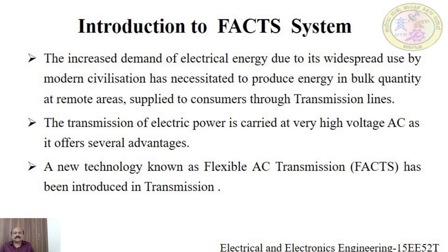First and foremost, the high voltage reduces the total amount of the copper material or conducting material used in transmission lines, therefore it becomes economical. The line currents are reduced, hence the losses will be reduced, and hence the efficiency of transmission increases. Moreover, it decreases the percentage line drops. Therefore, we can supply the power at good quality.